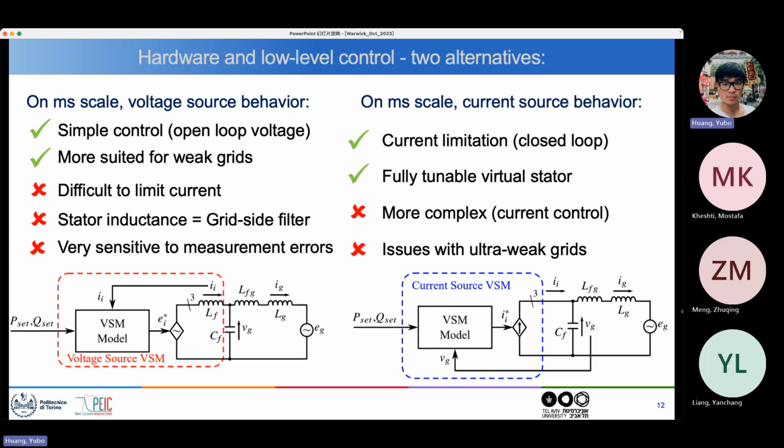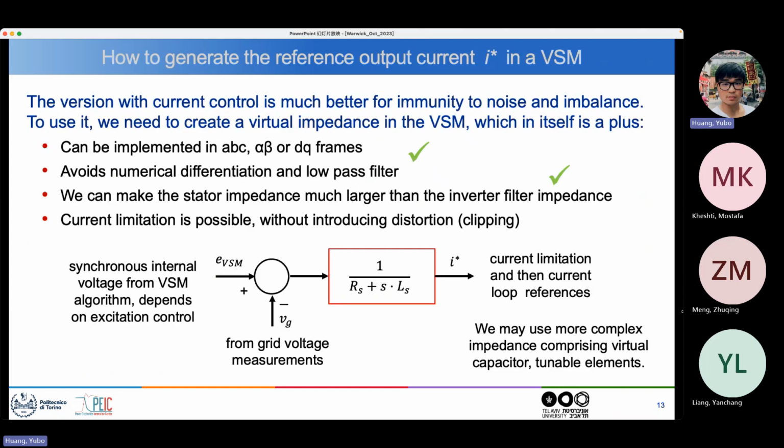Yes, it's not stability from any initial state, but it is almost sure. So the set of initial states from which it will not converge to equilibrium has measure zero. So if you are in a good choice of parameters, then you have this very strong kind of stability, almost globally asymptotically. For the grid connected generator, yes, for an infinite bus, one generator on an infinite bus.